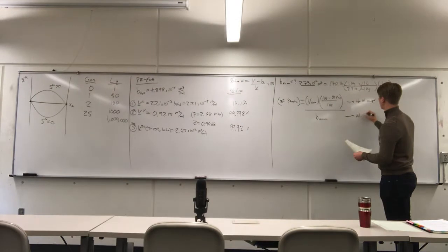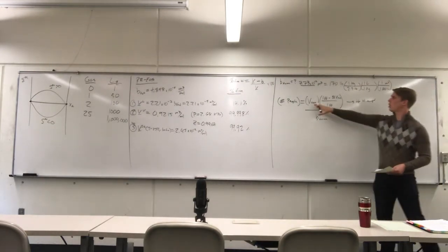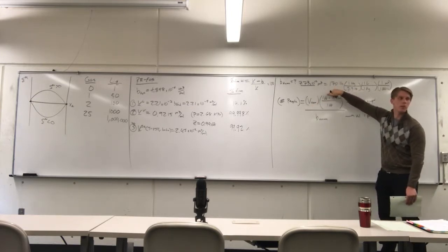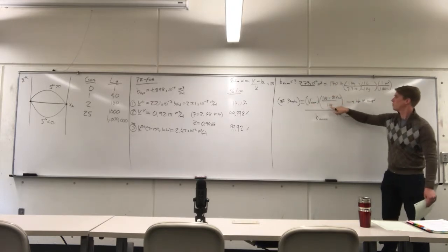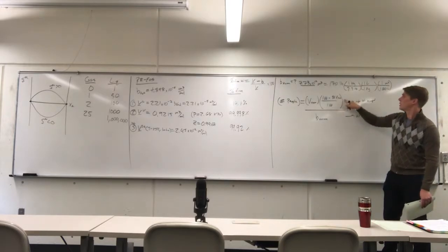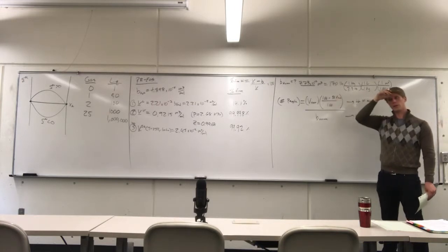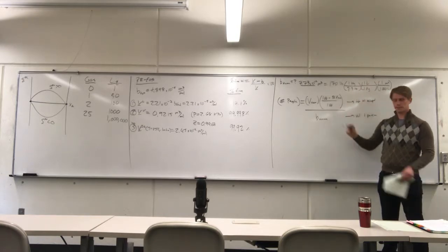And this is the volume of one person. We have the volume of the room, 100 minus the percent free volume, that's the volume occupied. I divide it by 100 to make that a fraction. So when I multiply the volume by the fraction of the room filled with people, assuming the same constant percent free volume, then I normalize it here. This is cubic meters occupied by people. This is cubic meters per person, so that flips from the numerator to the denominator, and that gives us units of people.